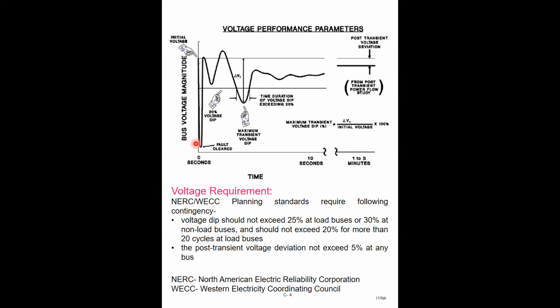All right, so you get a drop in the voltage, but when the fault is cleared, then again the voltage will rise. But it is possible that you come across some oscillation in the voltage profile. Thus for a few seconds following the disturbance, though it was a temporary disturbance, you come across a voltage oscillation.